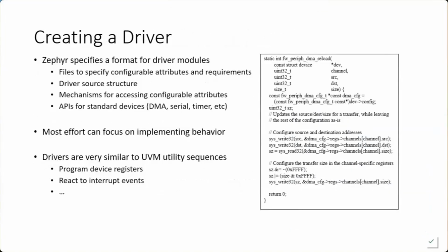Okay, so touching briefly on the process of creating a driver, and again, the paper goes into a bit more detail here. The Zephyr RTOS specifies a format for drivers in the system. It specifies the data types you have to use and the data structures you have to define, and how those fit into the driver framework such that you're able to configure the various aspects of the driver.